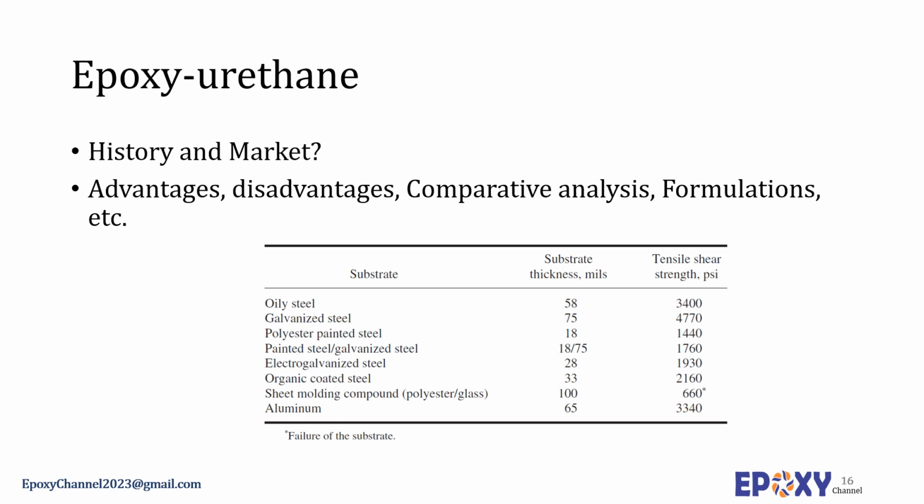There have been many attempts to couple the integrity, heat, and chemical resistance of epoxies with the toughness and peel strength of the polyurethanes. However, these attempts have often resulted in adhesive systems that display the worst properties of the parent resins rather than the best properties. This is due primarily to the significantly different reaction rates between NCO groups of the isocyanate and the epoxy groups of the epoxy molecule with the common curing agents. The isocyanate reaction is several orders of magnitude faster than the epoxy reaction.